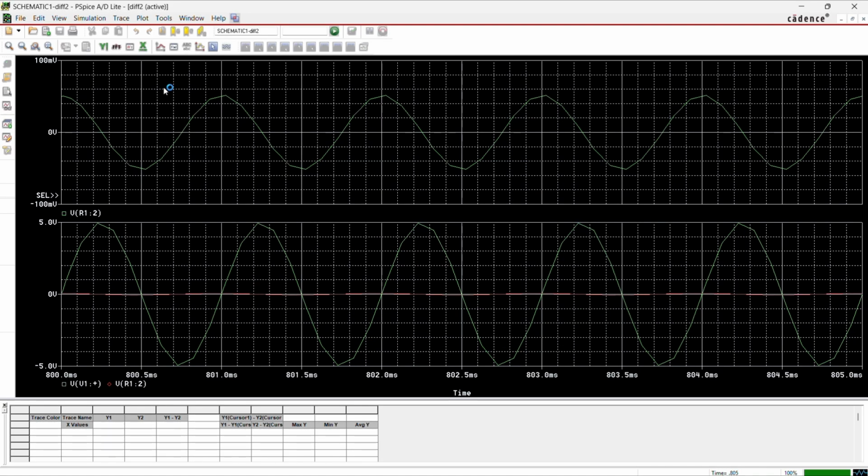Okay, the color is different because when you're using two graphs in the same plot, it'll be of different colors. When it is different plots, then it came as the same color. So I'll just remove the VR12 from the previous graph. Just click it, select it, and press the delete button in your keyboard.